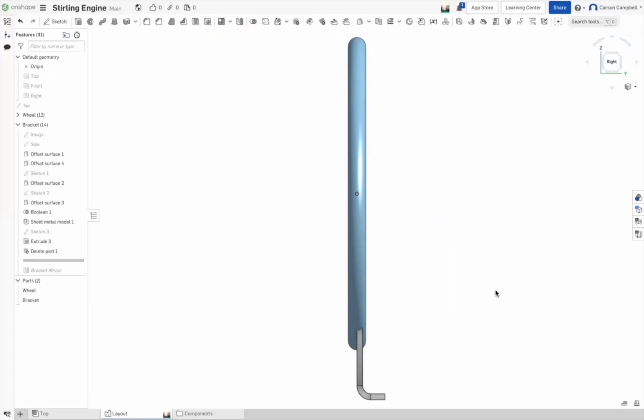In other words, the origin is in the center of the wheel. And I kind of want to keep that fact moving forward. I also know that the bracket is the angle moves to the inside. So what I'm going to do is, after we now have the bracket, but let's go ahead and let's translate the bracket. So up in the command, we need to find translate or transform, excuse me. And just go ahead and click transform.